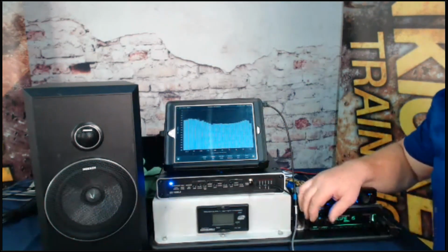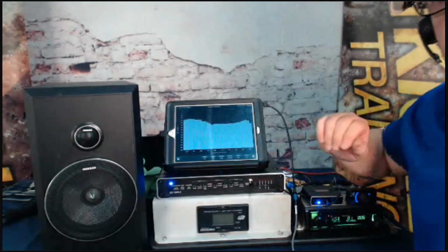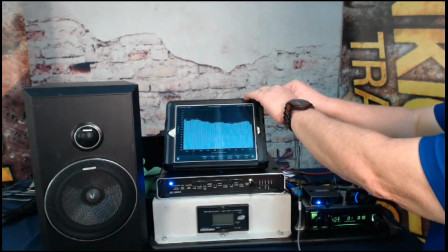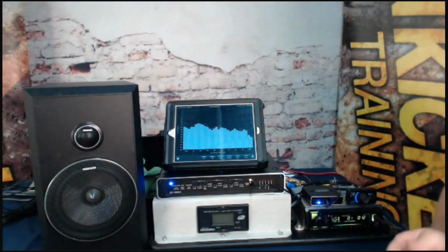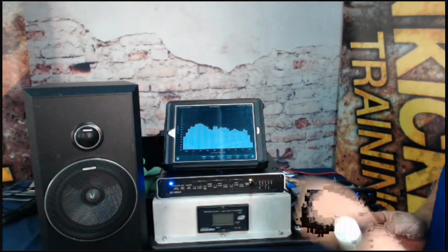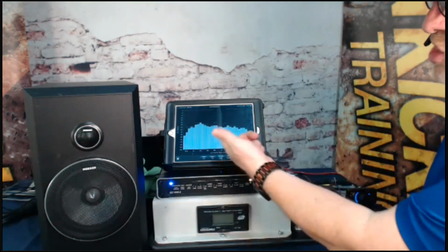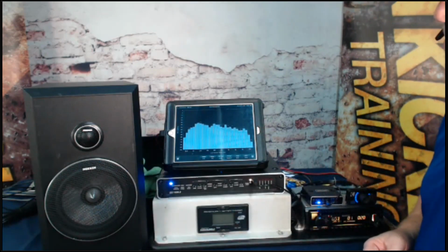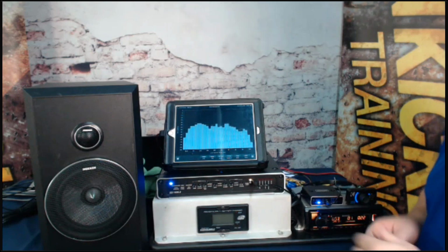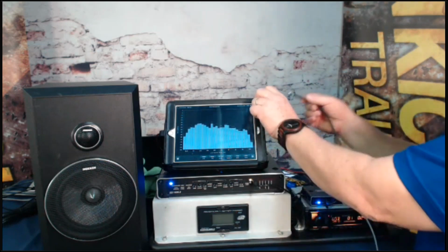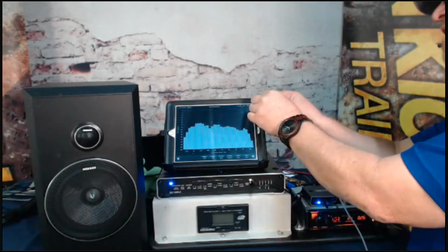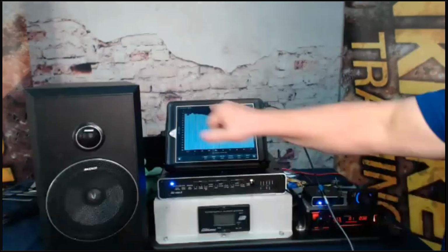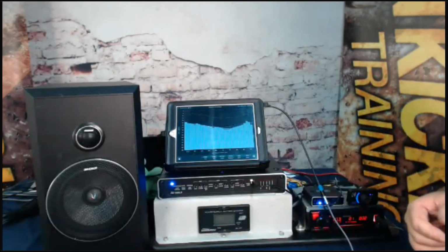So now I'm playing pink noise. This is measured right from the audio output. Let's see what it looks like if I'm using the microphone. Very different. That's the microphone. As you see, it changes with my voice, using the microphone to listen to that speaker. Very inaccurate. You can't use your ear. You can't use the microphone on the tablet. You have to use a direct hardline source. Now I've switched back over to the headset microphone.